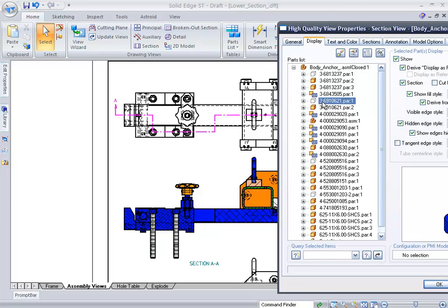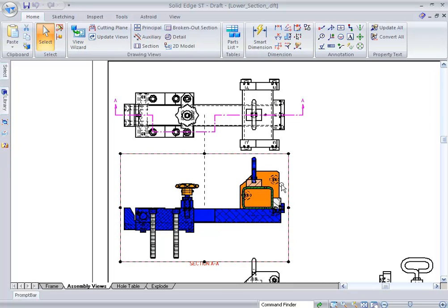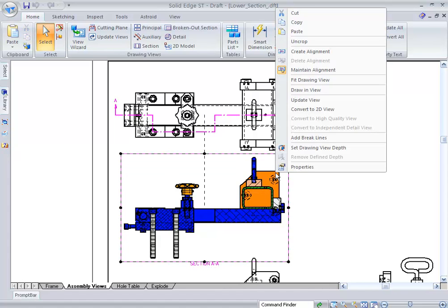The ones that are gray, they're not even visible on the screen. So if you hit the little eyeglasses, we're actually highlighting those parts on the screen that have been cut through, or whatever you're actually selecting. That enables you to do any kind of option over here to the right. What do you want to do with that? Well, maybe this one I just want to take completely out of that view, and you can see how quickly it is to take that out of the view and update that view. So you can customize this any way that you want.